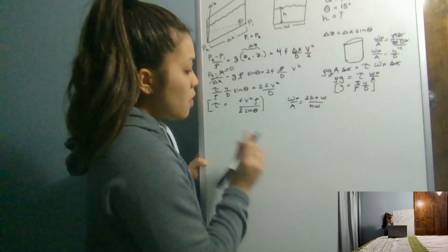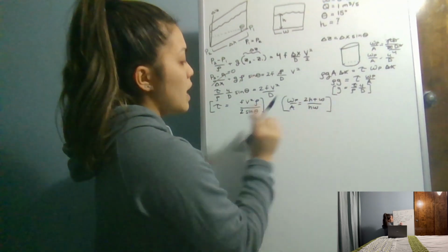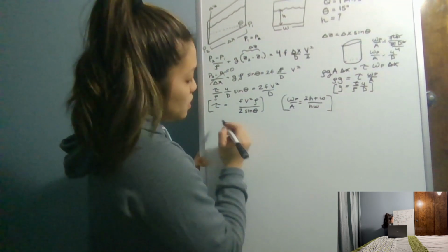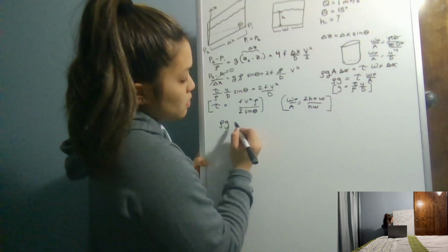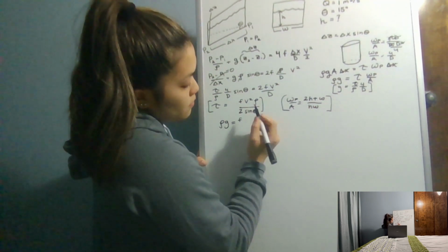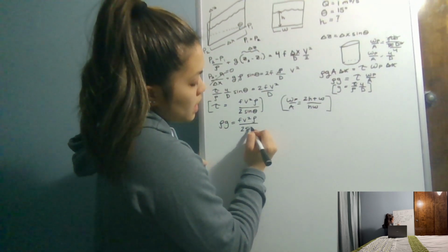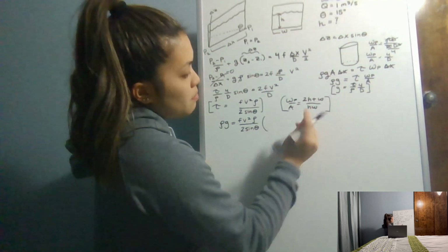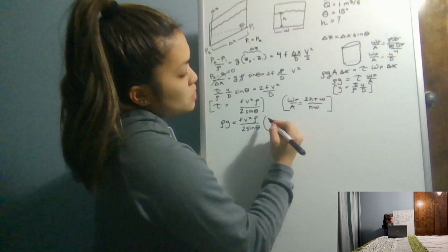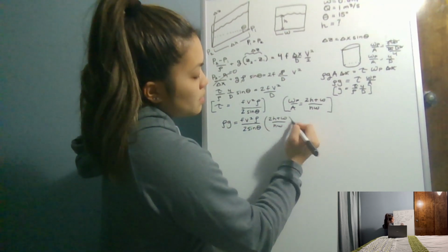And then we can plug this equation and these two expressions into this formula here. So we'll have the density times the gravitational acceleration is equal to, first, the shear stress expression: friction factor times velocity squared times the density divided by 2 times sine theta, multiplied by this wetted perimeter over area expression, 2 times the height plus the width divided by the height times the width.